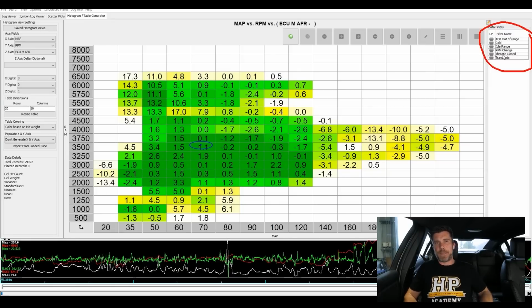And that's where we're going to be in that overrun region where we've potentially got our overrun fuel cut active. We're going to be measuring very lean air fuel ratios because we've got unburned oxygen going through the cylinder. So the lambda sensor is going to be measuring that fresh oxygen and measuring lean. So we can turn on a throttle close limit.